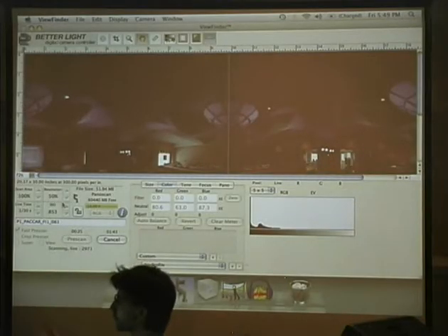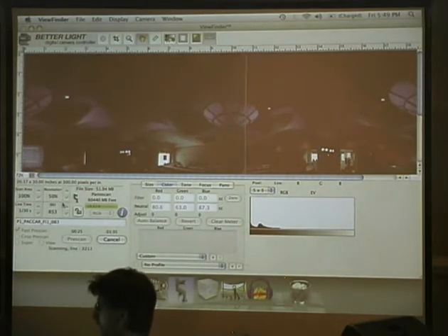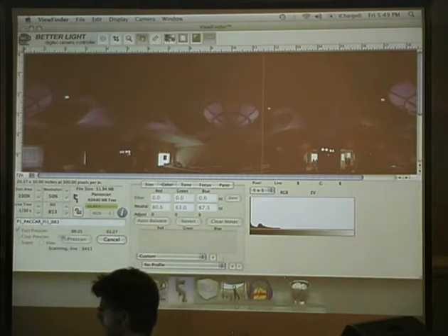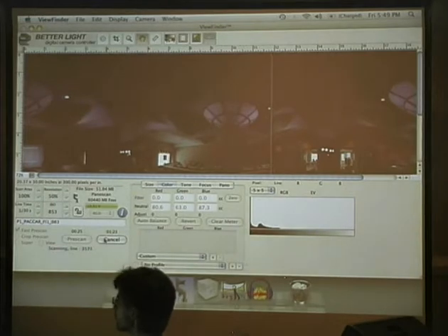Do you want to talk about file size with these? Yeah, pixel resolution? So right now, we're operating at a 50% resolution. If we crank that up to 100, it'll take roughly double the amount of time, or quadruple. I don't remember exactly how that scales, but adjusting the line time, the shutter speed for every vertical segment, also affects the scan time. So we've had some scans that have taken up to 20 minutes or so if we're doing a dark room at full resolution.